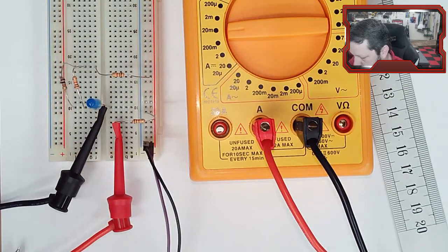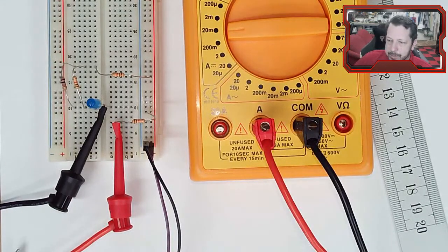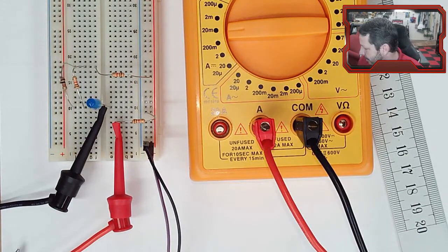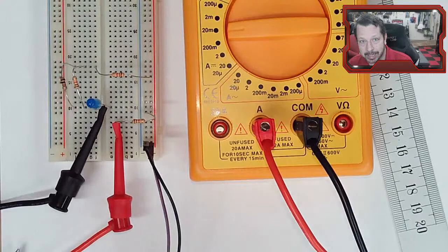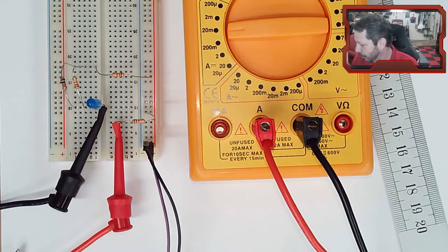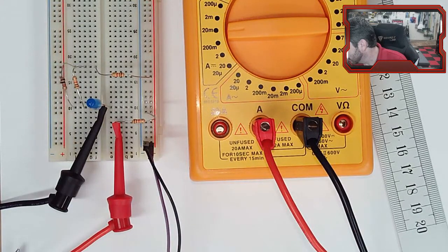Now I've got the voltage set. Normally, I've got a power supply off to the side over here, so you can't see it. So you turn those off, like the voltage that you want to supply. You turn that all the way off before you actually turn it on. Otherwise, there's a chance that you left it at some position where it's trying to supply 20 volts and you're just going to burn up your LED. So we'll gradually crank it up here until we get,